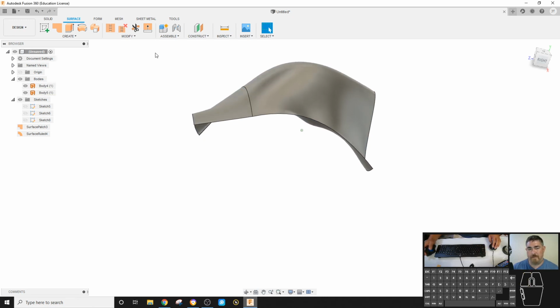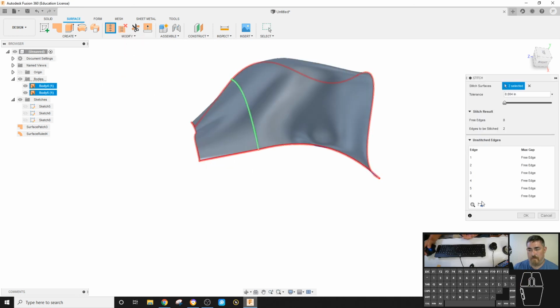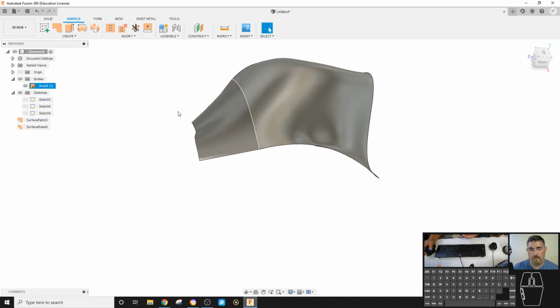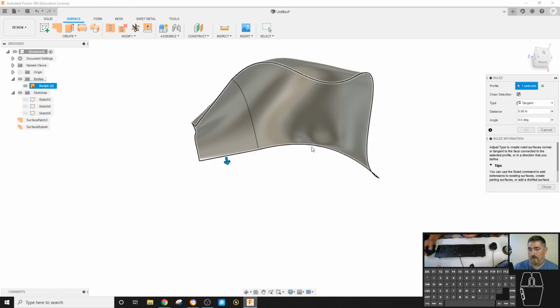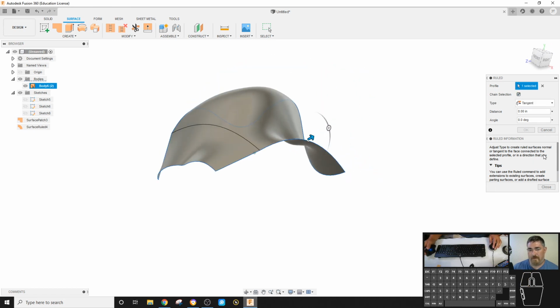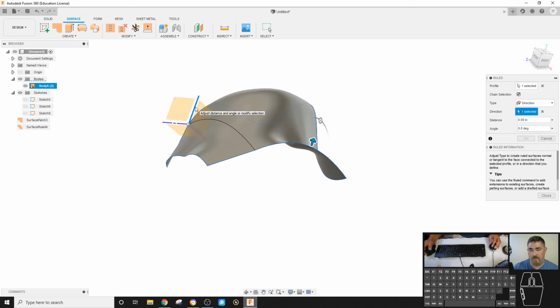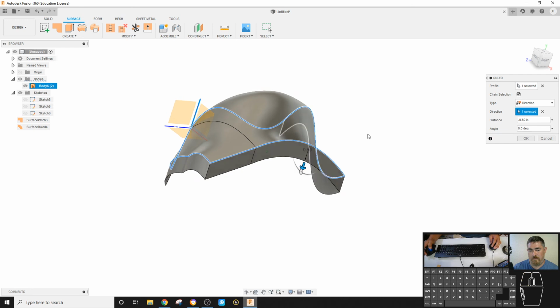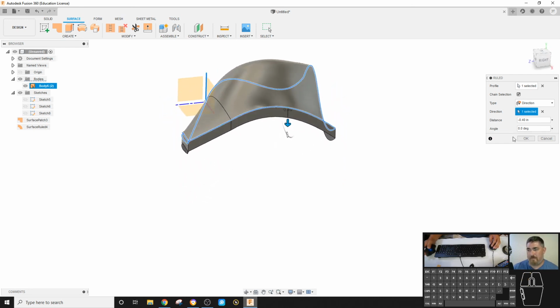So those are two separate pieces, so I can join those together by stitching them. Now that's one edge there. Now if I go to ruled surface, I pick it, it makes the entire outside. So if I told direction that way, I could come down a certain amount, kind of like adding the thickness to it or whatever.